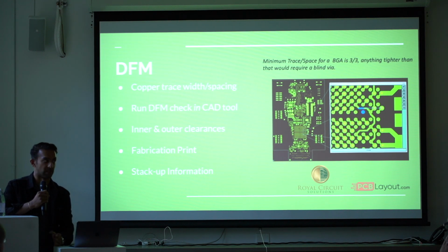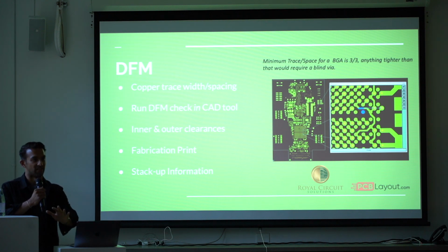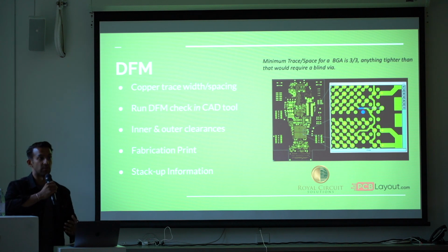buried via, especially if they're small, that's going to be 3 days, because now you have 2 lamination cycles, 2 plating cycles, potentially 2 drill cycles. That's double the amount of people at the touch. It's got to go through different cycles. Oh, also, we're swamped, and we're a quick turn shop, and we have like 15,000 customers doing it. Not that you should be penalized for that, but just knowing that certain things will require double the machine time, double the processing time, that isn't always clear.